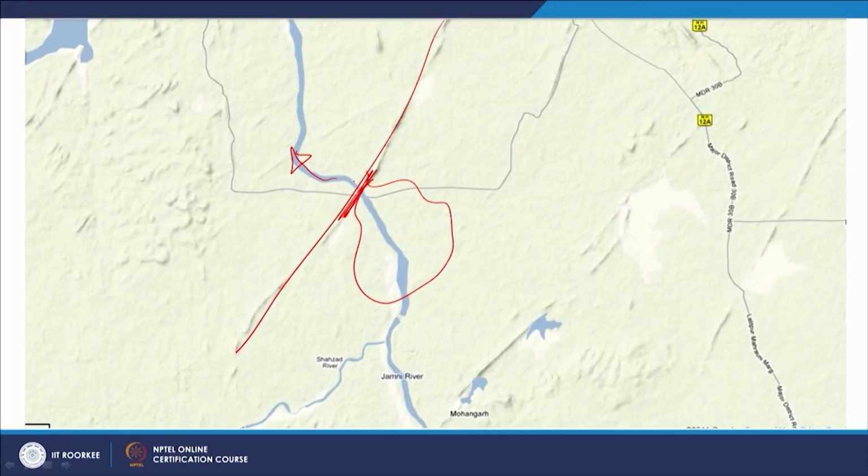Another thing is how to further assess this situation. You remember that we did hydrologic modeling in GIS, and we created a drainage network. While discussing this surface hydrologic modeling, in the beginning I said there is an assumption that each drop of water will flow as surface runoff. That assumption is okay, we can exploit even that assumption, and just by adding one more layer, we can find out which areas will provide better groundwater recharge.